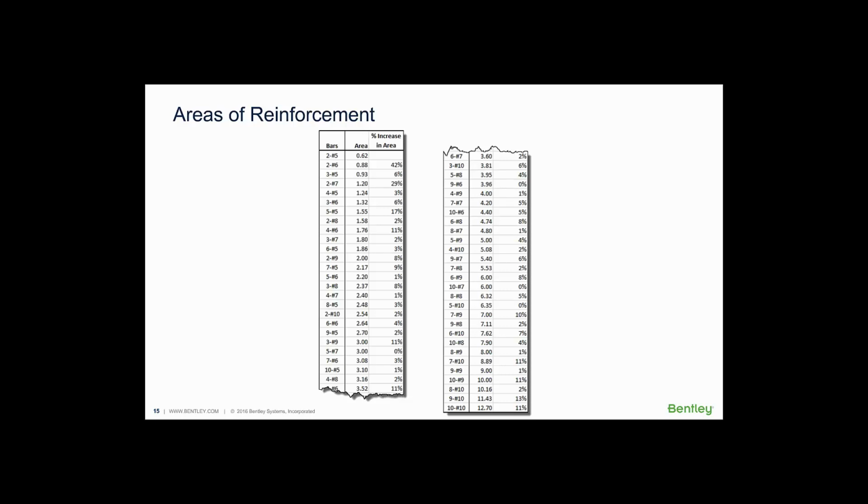So you can see, in the case of rebar, it's a finer jump than it is for steel beam sections, but there still is a jump, 11%, 3%, 8%, 9%. So we go through all this effort of doing an analysis, but when we finally go to actually do the design, we're picking bars that usually don't exactly satisfy the demand.